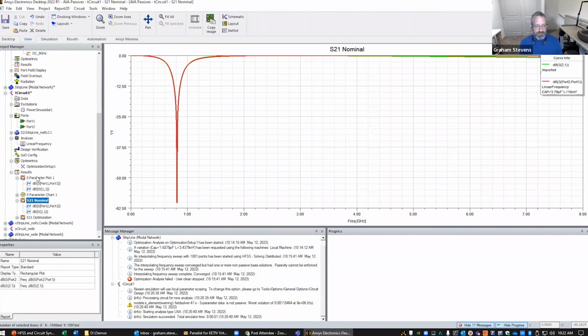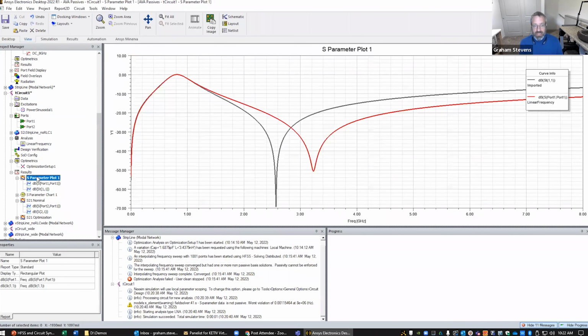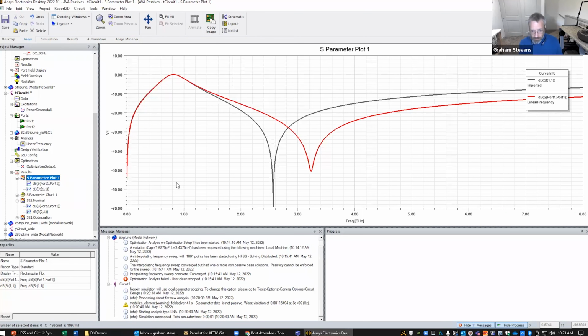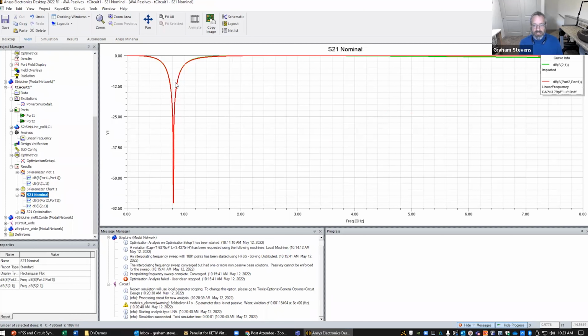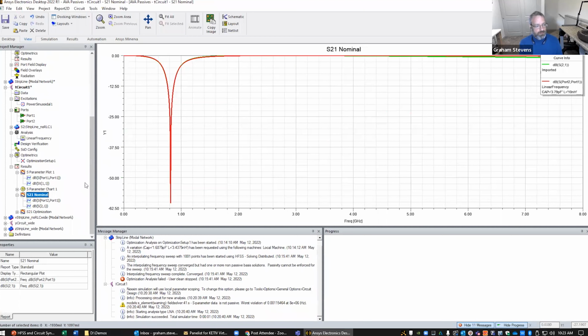in terms of trying to optimize your RLCs, and they may be slightly different, and you have to again play with what level of accuracy I need to get these closer. I can pull these a little closer if I increase my accuracy, or model a different level of detail. So in this particular case, I'm just interested in this S21, and these are almost identical. And so therefore, I'm feeling pretty good about the circuit model giving me the types of results that I'm looking for.